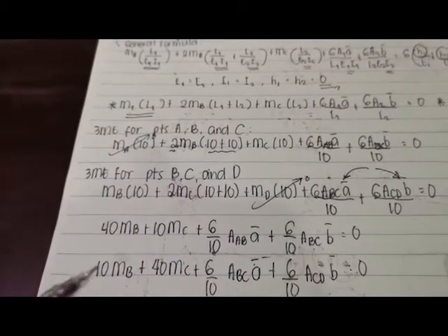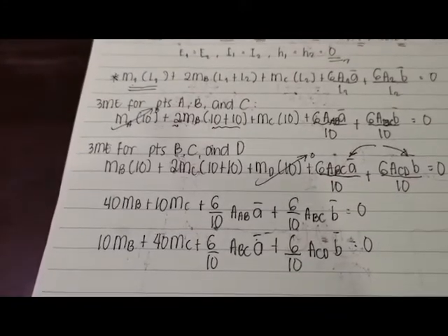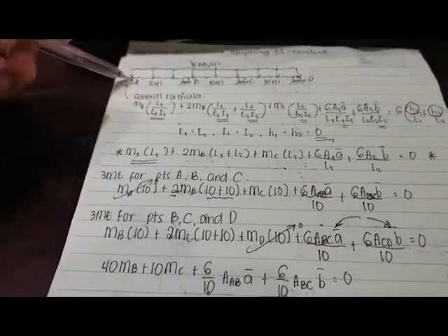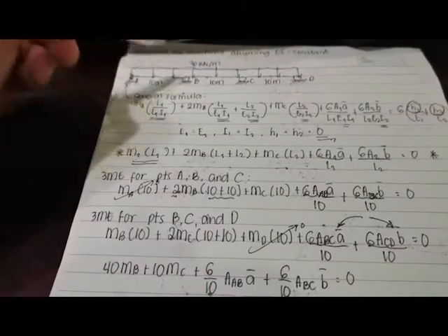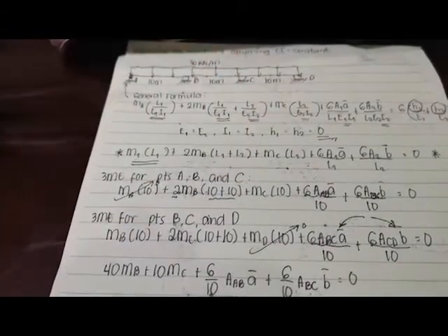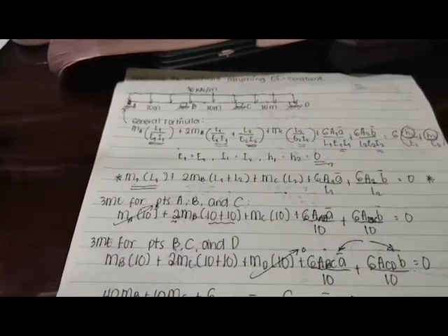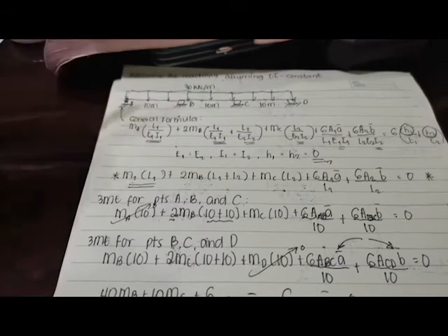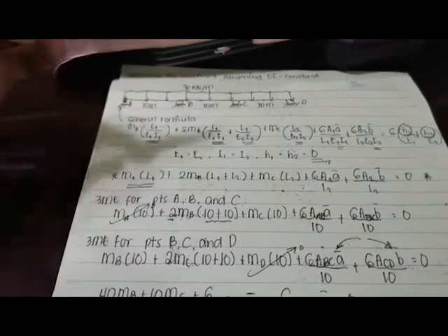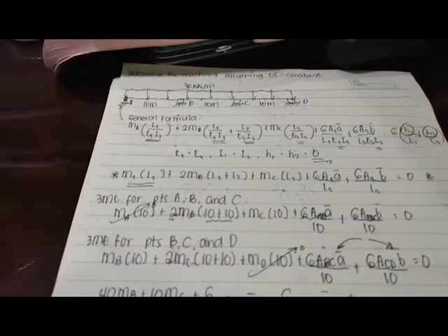This is the first moment of area of our spans when we remove the internal moments. We've learned this principle from the method of consistent deformation: when we consider the internal moments and internal forces as redundant, for example by placing an internal hinge here, we can separate the spans like simply supported beams.